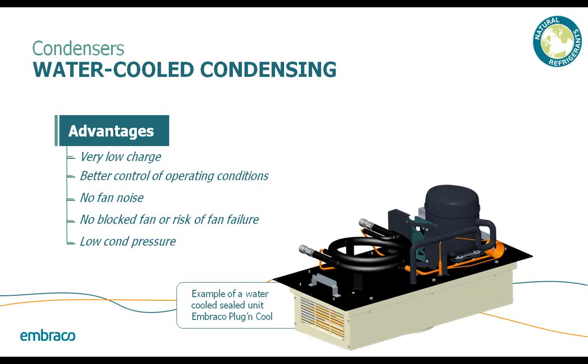Also, you have no fan noise because a fan is not required to do water-cooled condensing. However, if you do have a fan-cooled compressor, some airflow does need to be maintained across the compressor shell. You don't run the risk of having a blocked fan failure, and you can get lower condensing pressure if you use cooler water. You can reduce the condensing pressure, and with that you get more capacity out of a smaller displacement compressor than you would get using air-cooled condensing.